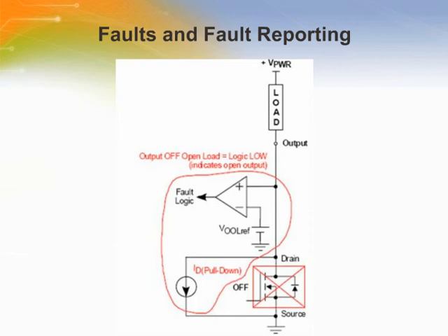Analog power ICs have many combinations of fault detection and fault reporting. Some devices detect faults and use the information internally to trigger protection systems, but do not output the fault. Most ICs do output fault information for diagnostic purposes. This information, when available to the user, is very valuable for troubleshooting purposes.